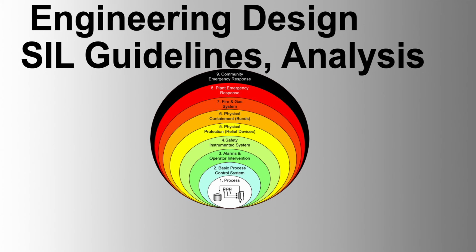Modeling of elements in PES arithmetic logic solvers. Programmable electronic systems, PES, can vary significantly in architecture. Typical architectures include 1. Small single-board PES with integral I/O. 2. Multi-board PES with main processor module and processor-based I/O modules. 3. Multi-board PES with main processor module and I/O chassis with I/O processor module and non-intelligent I/O modules.